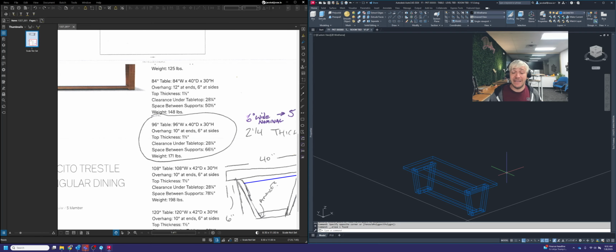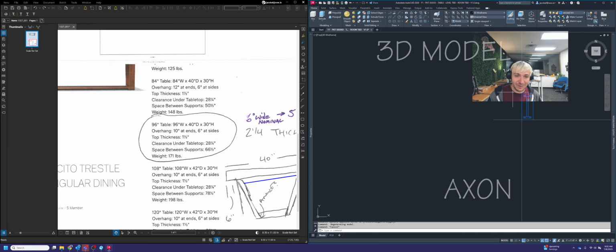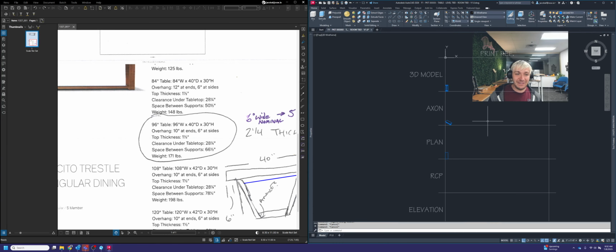I don't know why. I cannot explain how that worked, but it's almost like it sliced it and deleted it. So you've got to be really careful about that. I usually just delete it to be on the safe side. Could be old, could be fixed by now. Autodesk probably already addressed the problem, but I don't want you to fall into that same bucket that I did. So let's just pretend that that problem still exists, and we're going to delete that section plane to make sure that we don't have that issue.